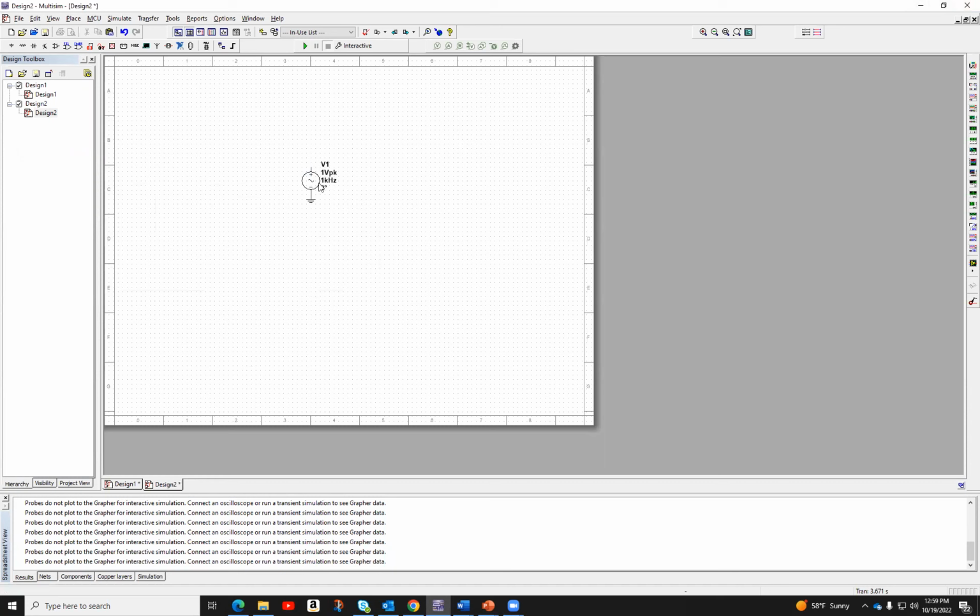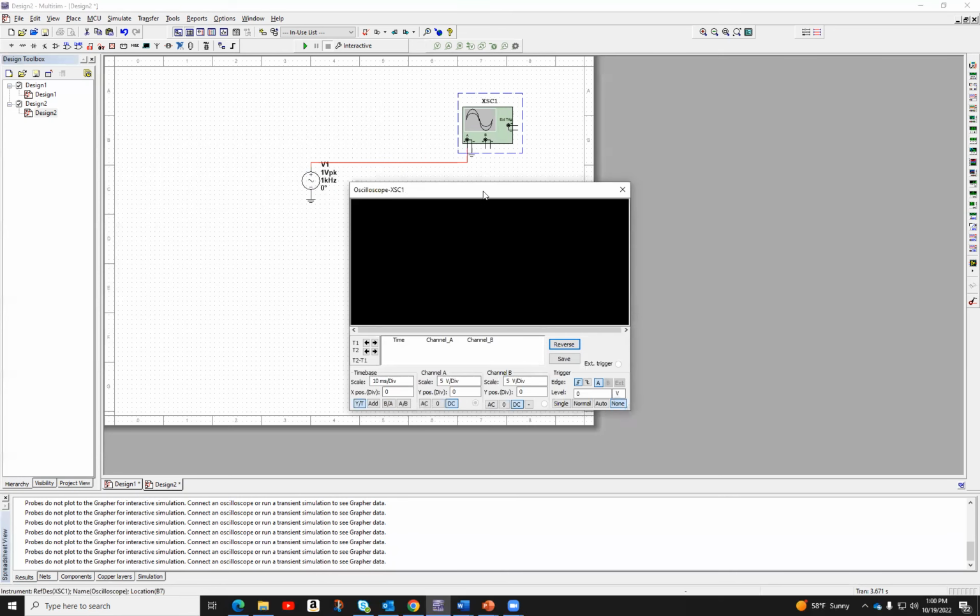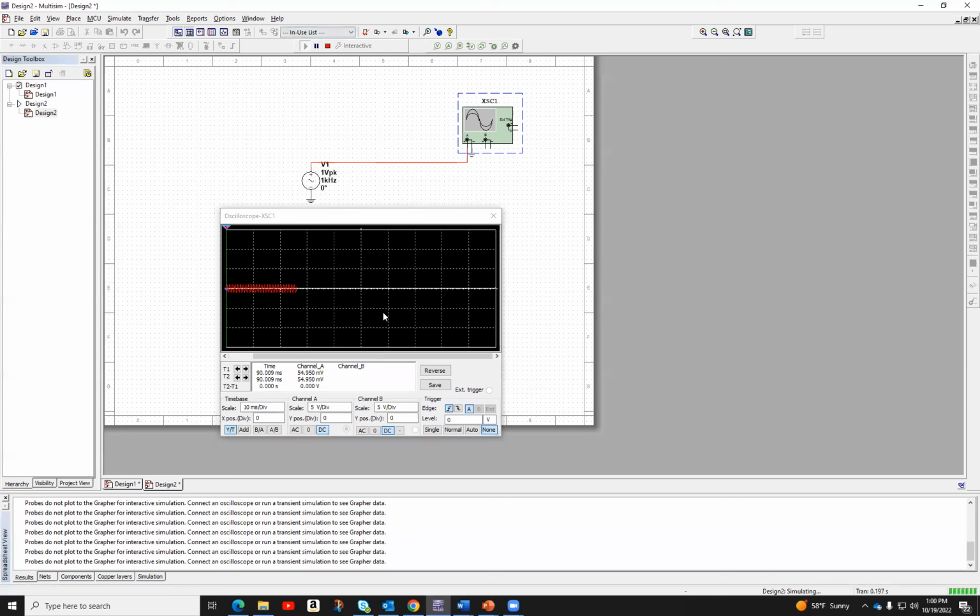And the 1 kilohertz means how fast it's going to change, because it's a periodic signal. Last time I used a simple scope, the default scope, remember, to measure that signal very simply. Let me just do that again. Sorry, let me ground this. I'm going to need another ground. So very simply, if I double click on this and run it, I will see the signal here.